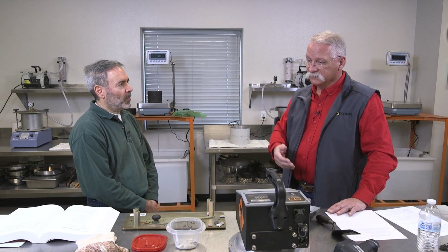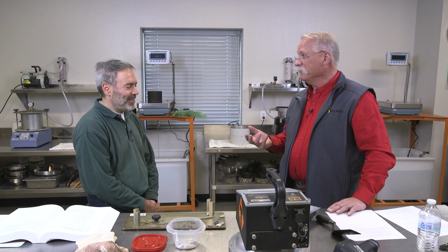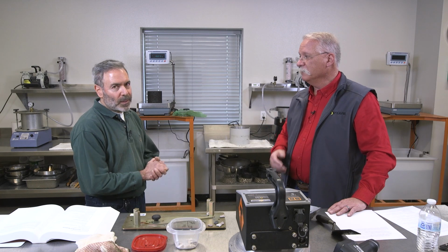We got to take representative samples. We got to follow the random numbers. And we didn't talk about random numbers, but that's a real key aspect of this whole thing as well. So we're not sampling everything. We're only sampling a tiny fraction of that material. You want to talk about it? Yeah, well, it comes down to acceptance. FHWA requires any kind of acceptance to be based on a random sample. So that's the requirement for FHWA.